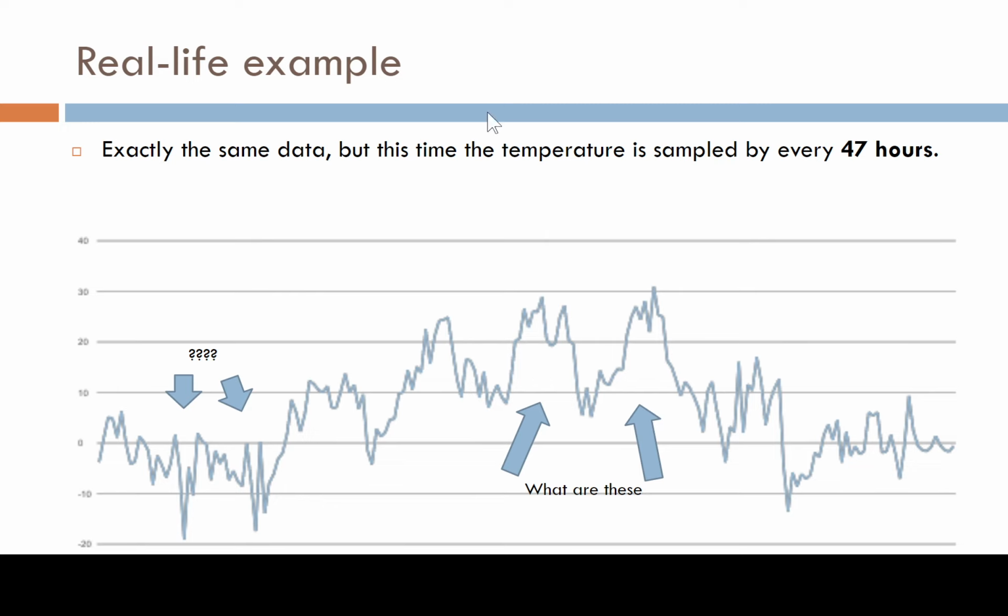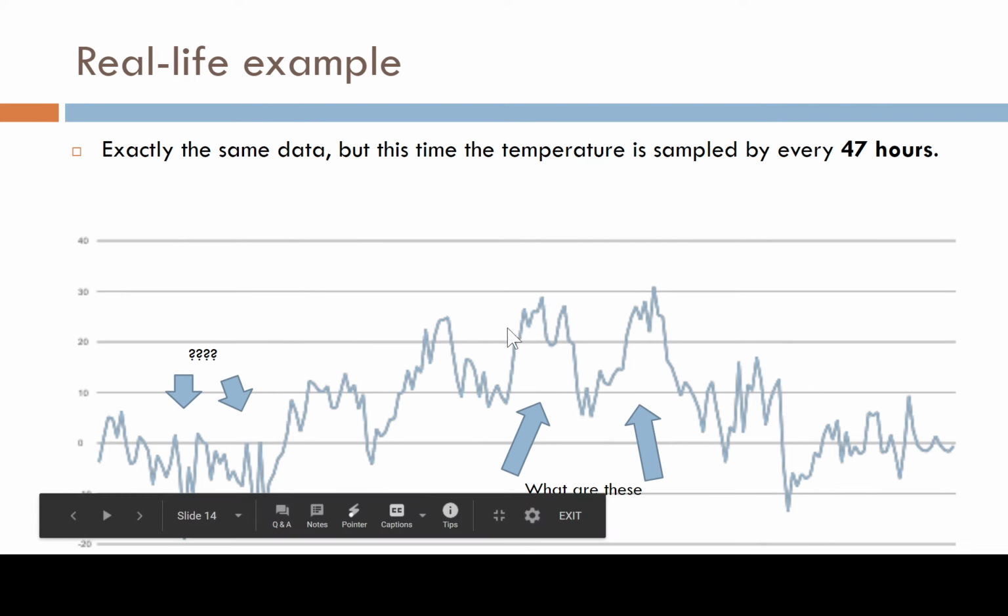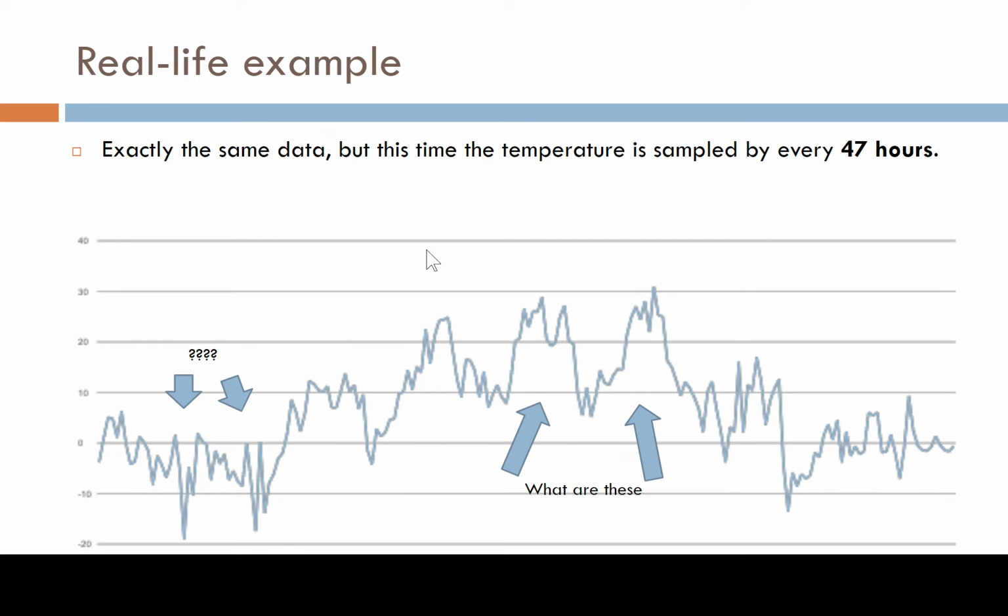So could it be that during this month, about June, it would be 10 degrees, then about 20 degrees for July, and then August 10 degrees, and then again 25 degrees? This is coming from the aliasing. So you sampled day and night temperatures and mixed those. Some of those are daytime, I would say, and these are nighttime temperatures. Okay, so sampling matters. It needs to be fast enough.